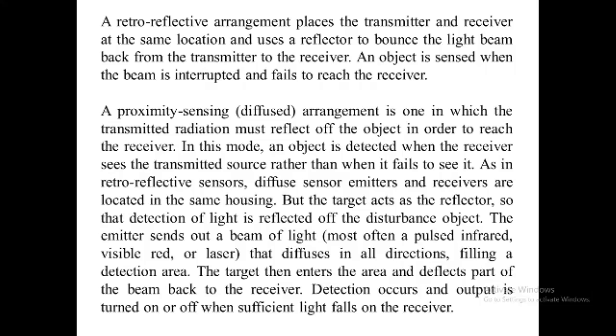Let us see what purposes diffuse sensors can be used for. Basically, a diffuse sensor can be used to detect multiple objects on a common conveyor system, to detect transient objects, to detect the fill level inside a container, to detect the presence of parts, boxes and web materials, to detect specific identifying features, to determine an object's orientation, and to detect unwanted conditions for product inspection tasks.